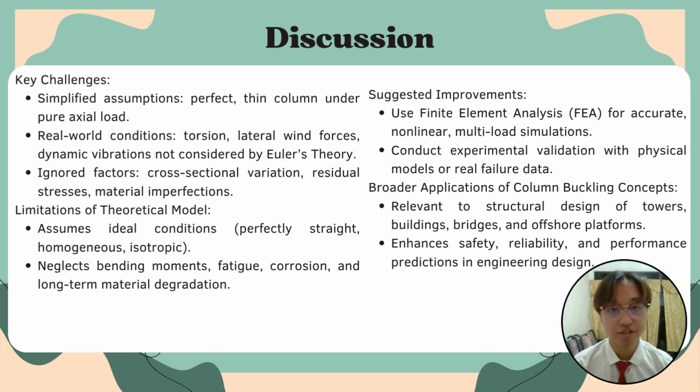As for the discussion, we can say that the key challenge is the simplified assumption of a perfect column under pure axial load during the wind turbine column buckling analysis. There are several challenges that surfaced, which is that wind turbine structures actually encounter complex loading circumstances, including torsion, lateral and wind forces, and dynamic vibrations.